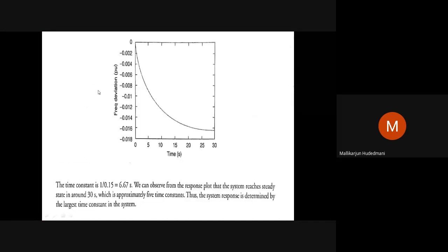Now I have a problem which makes you think in a split way. There are 4 machines. Inertia constant of each is 5. Then the total H of the plant becomes the number of machines multiplied by the individual inertia. This is the grand value of H we should use in the numerical solution. My intention is to show you that when several generators are put in combination and H of each is given, what is the total H? Since the machines are identical, we multiply, so we calculate 5 into 4 as the grand H.